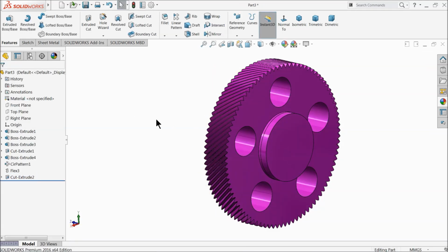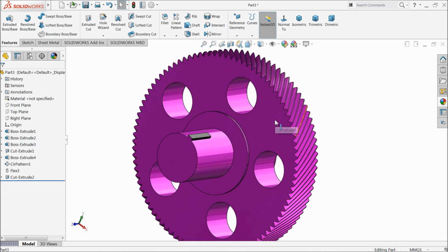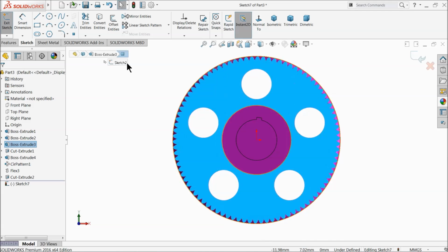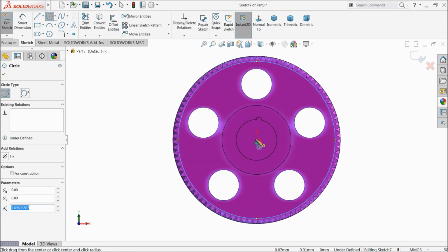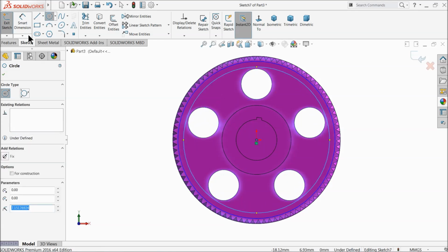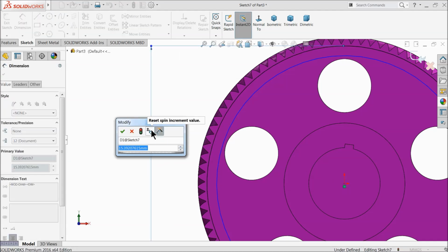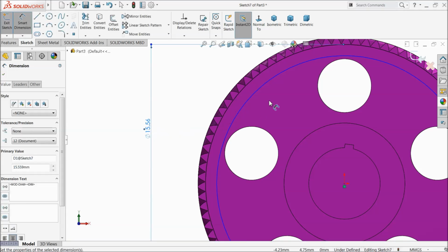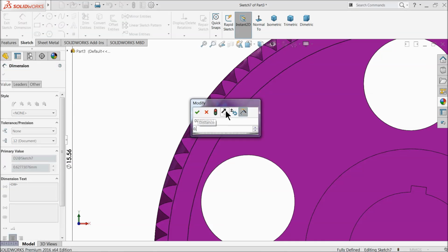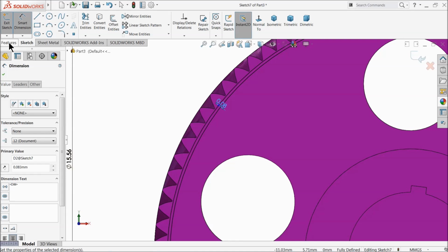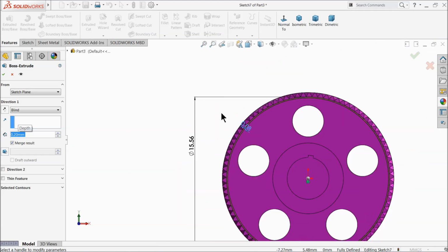Okay, that's it. Now select this back surface, sketch normal. This is front surface actually. Now here create 2 circles. Now let's try the outer diameter, 15.559 millimeter. Now let's keep this gap 0.083 millimeter. Now extrude this face 0.2 millimeter only.